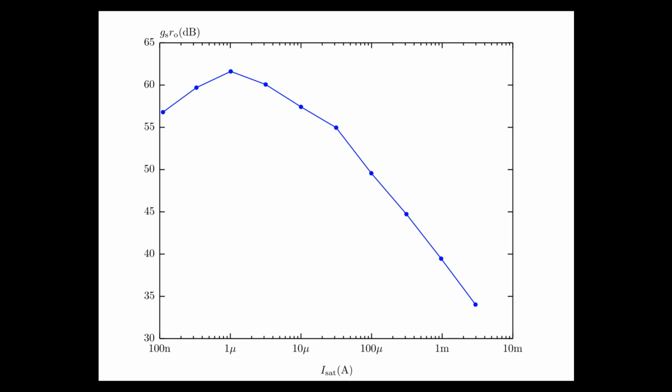So that theory is actually quite good, and that's pretty much because by the time we're up here, we're in a region where the early voltage is more or less constant, and the model that we have for this source conductance changing inversely with the square root of the current is actually a pretty good model. And so the net effect is that this fall off of intrinsic gain with saturation current follows the simple theory quite well. So this just gives you an idea for typical numbers for these kinds of things. So 40 dBs here is a factor of 100.